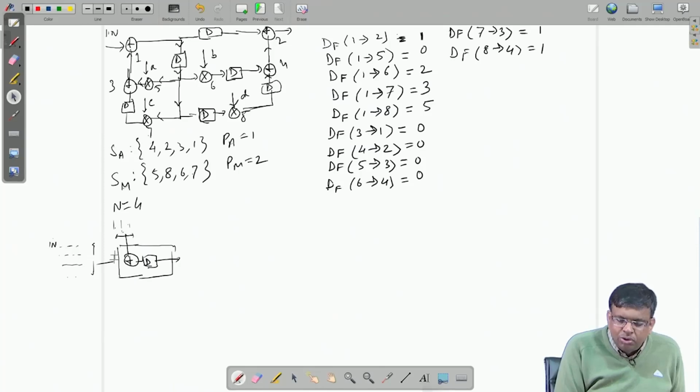Then it will carry out a summation and it will get delayed by one cycle. So, adder output, the output is born, but internally also delayed by one cycle. So, it was born in what schedule? At cycle 3, because 0, 1, 2, 3. 3 is the schedule of adder 1. So, at cycle 3, this fellow is touching the appropriate inputs like in from here, carrying out the job of adder 1, okay, but there is an internal delay that is for pipelining.